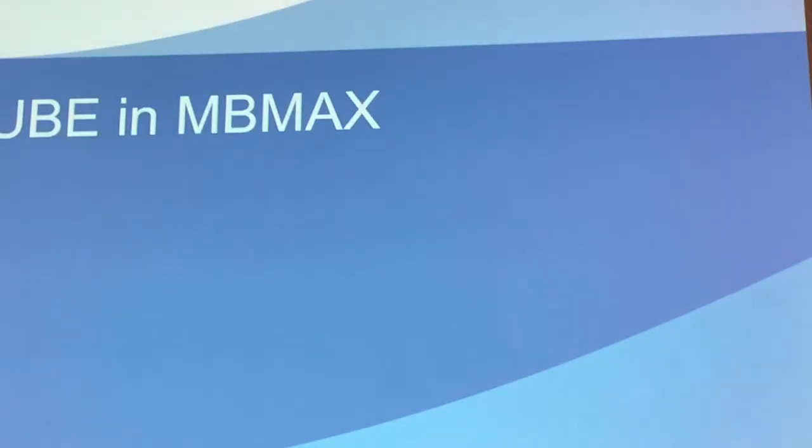Okay, so the other thing I want to go through is actually Cube. Cube is an automatic cleaning algorithm that they use for multi-beam. Usually, after you do the manual cleaning, you can do a cube cleaning to make it perfect. But for cube cleaning, it's only a fine-tuned cleaning, so you can't do major cleaning. That means if you have a spike, the cube will only take out the spike based on the filter size that you put. So if you want to use cube, the best way is to always use manual cleaning first, then after that you run your cube.